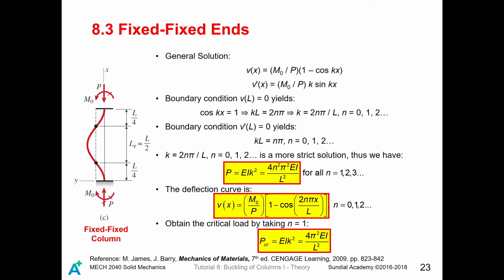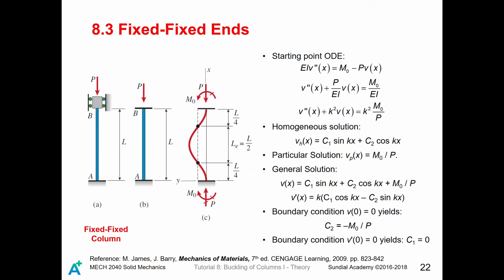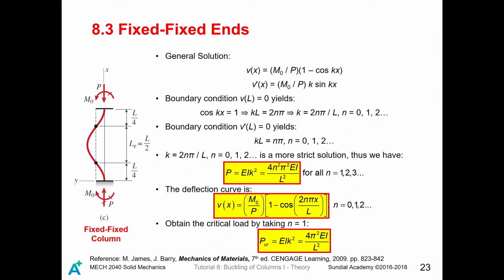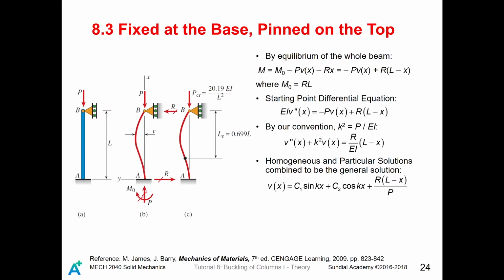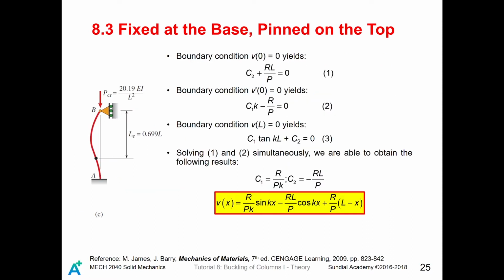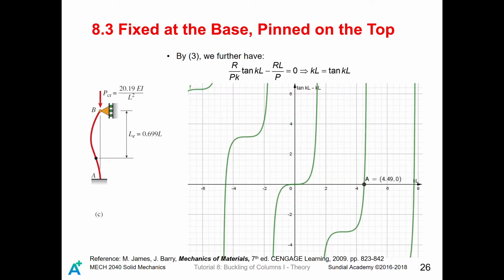are rather similar. So one special thing I want to talk about is in the fixed at the base and the pin on the top case, when you do the differential equation and solve it all the way, you will find eventually you get KL equals tangent KL, but this cannot be solved analytically, but we can get the solution of K by using some plots.